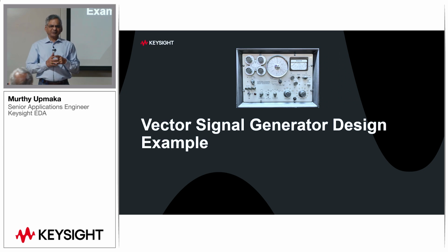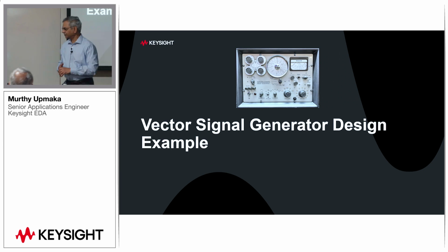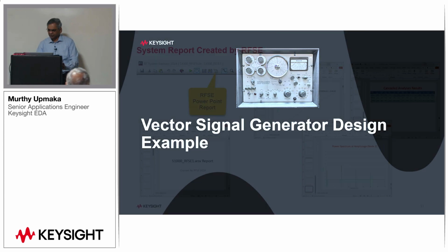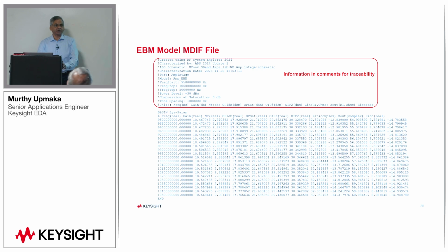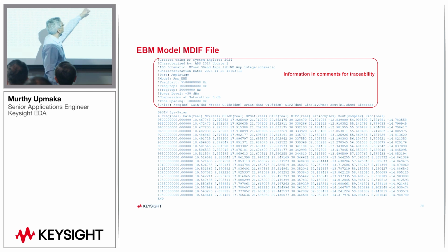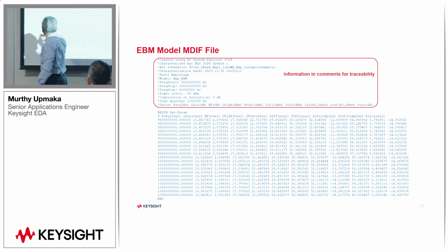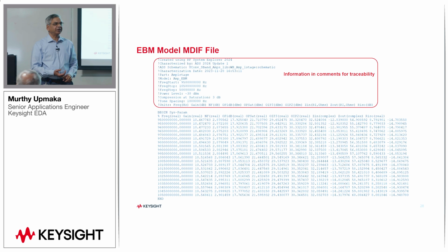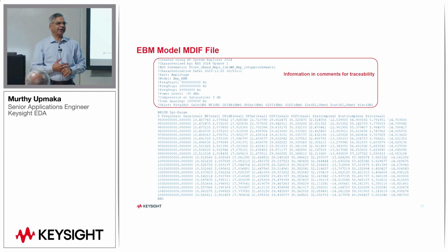Coming to the amplifier, there are so many ways to model amplifiers, depending on the context. Starting with a linear amplifier, it can be as simple as capturing S-parameter data with noise parameters, of course. Going a little bit more, in the extracted model, what I'm capturing here is gain, noise figure, 1 dB compression point, the whole thing. If you capture that as a function of frequency, temperature, or bias, it becomes an amplifier model.